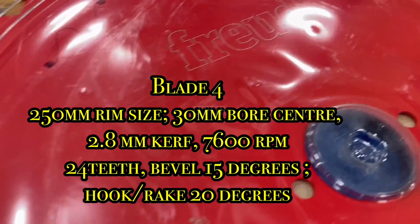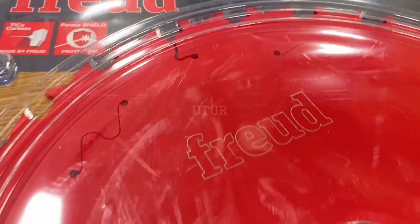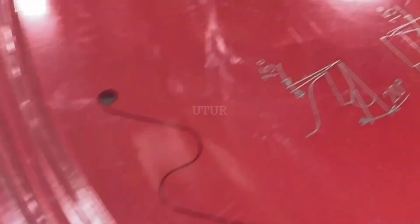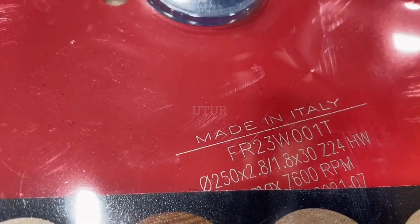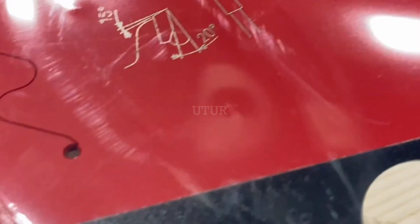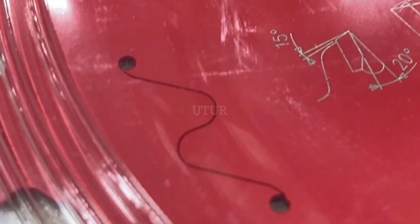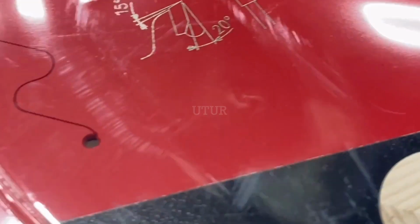The next blade has got a 250mm rim size, a hook or rake angle of 20 degrees, a bevel of 15 degrees, a 2.8mm kerf, and a 30mm center bore. So, at first glance, the 24 teeth suggest it is a ripping blade, but when you look a little bit further, the bevel at 15 degrees suggests it is an all-purpose ripping and cross-cutting blade, but not so fast. The hook angle on a typical all-purpose blade is anywhere between 15 degrees to 20 degrees, whilst blades designed specifically for ripping are usually 20 degrees.